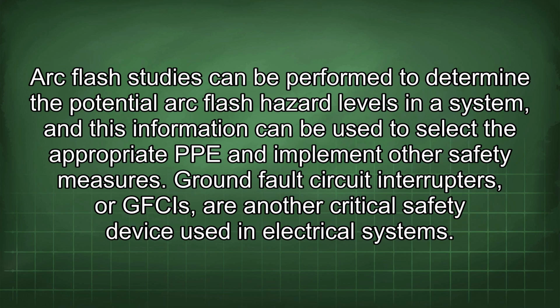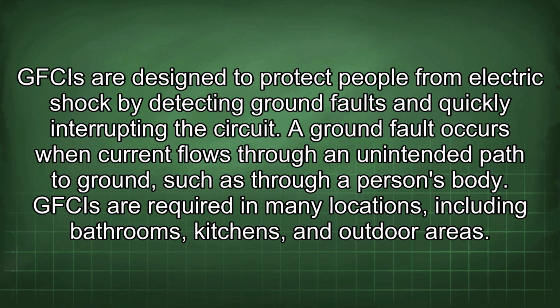Ground fault circuit interrupters, or GFCIs, are another critical safety device used in electrical systems. GFCIs are designed to protect people from electric shock by detecting ground faults and quickly interrupting the circuit. A ground fault occurs when current flows through an unintended path to ground, such as through a person's body. GFCIs are required in many locations, including bathrooms, kitchens, and outdoor areas.